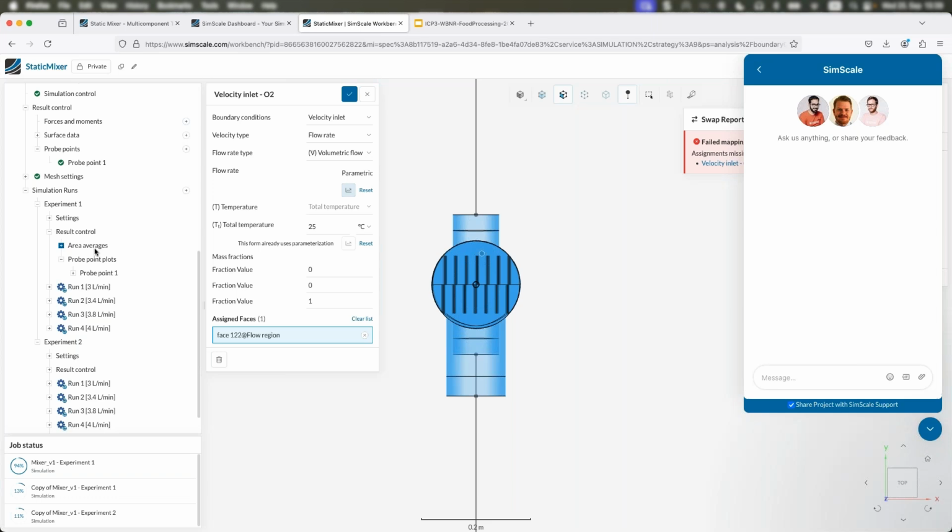I can give you an example of a case study that we previously did. It's just one case study. As an example, I'm sharing this with you, where we were able to do a shape optimization for a valve by connecting these two tools, SimScale and a CAD package, through the API, and ran about 900 simulations in 1.5 days, literally about 42 hours. There were about 14 constraints on the shape of the valve, and the objective was to optimize the flow rate, the CV value through the valve, and that's the simulation lead times that you're looking at. So that's what is possible right now.